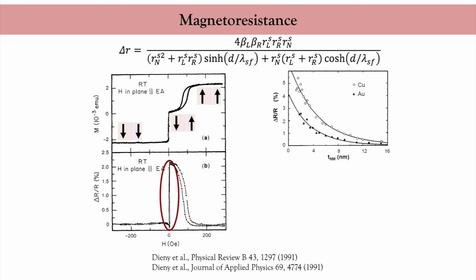If you increase the thickness of the spacer, you shall observe a regular decrease of the magnetoresistive signal, as observed here. Now it's important to mention that this decrease is not solely attributed to the spin relaxation taking place in the spacer. It is also due to the fact that adding more spacer material enhances the overall resistance. Therefore, when we look at the ratio between the magnetoresistance and the resistance of the full device in the parallel configuration, we end up with an additional algebraic decay.